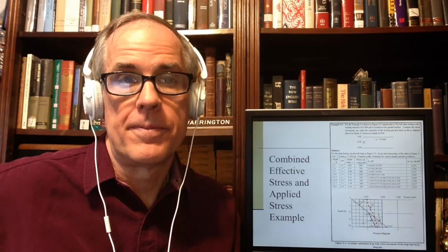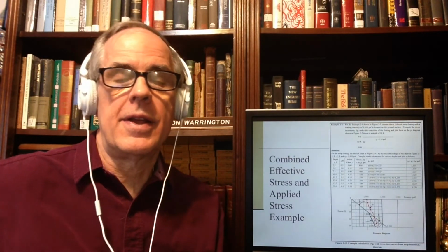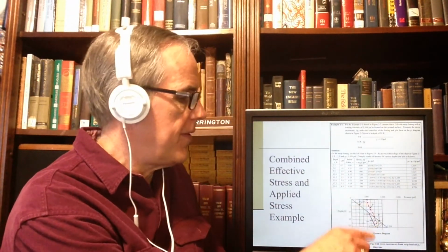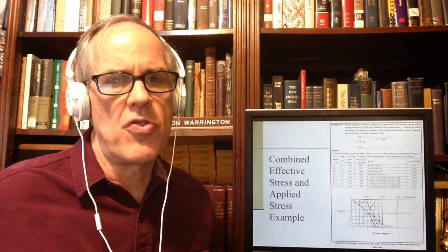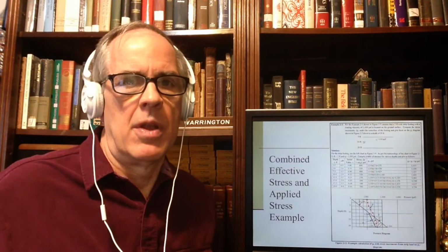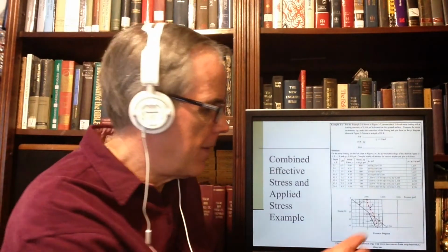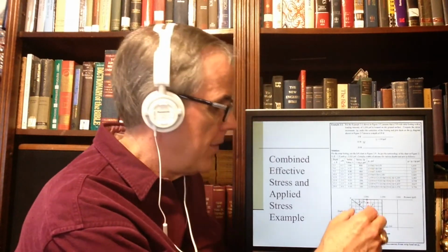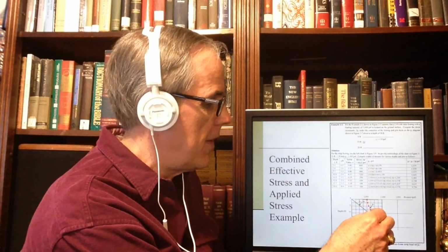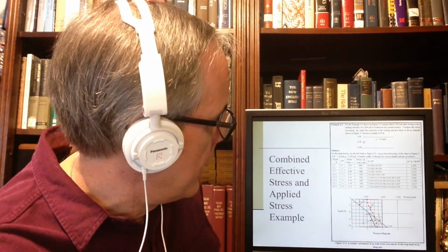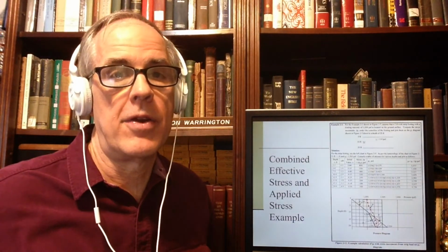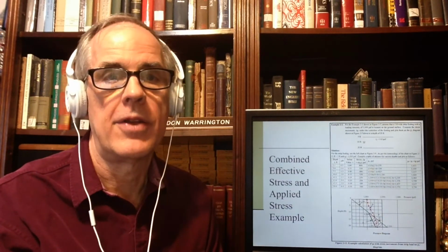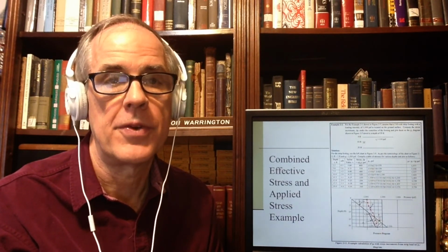In this case, you've got pretty much uniform soil conditions. By the time you get down to the water table, the difference between the two stresses is much smaller. In fact, it goes from 800 at the top to 320 at the water table, so it's not that much.